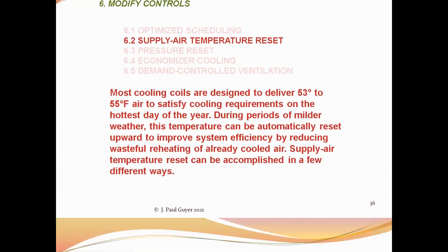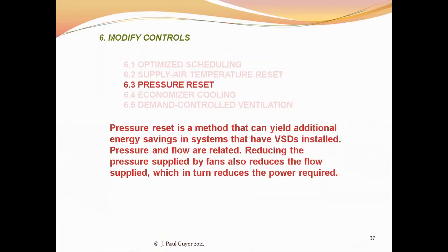Pressure reset is a method that can yield additional energy savings for systems that have variable speed drives installed on the fan motors. Pressure and flow are related. Reducing the pressure supplied by fans also reduces the flow supplied, which in turn reduces the power required. So pressure reset.